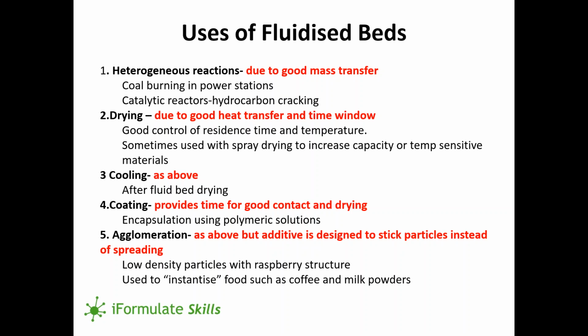You can use the same process or the same idea, but instead of having a fairly dilute polymer solution, if the liquid you're spraying on is quite viscous and doesn't have the chance to spread around the particles before it dries, then as the particles come together with the sticky surface of the liquid on top of them, they'll stick together and they'll start to agglomerate.